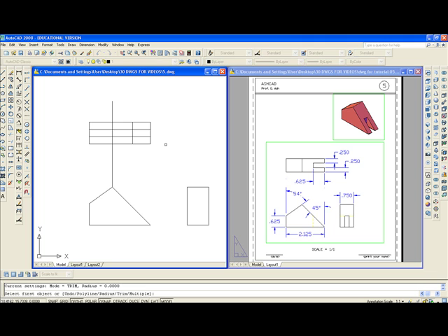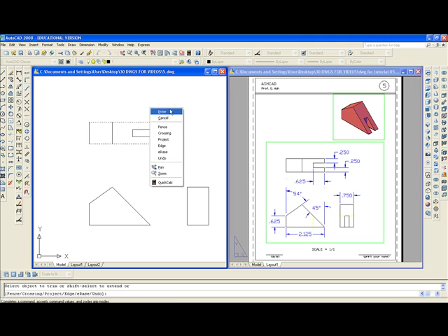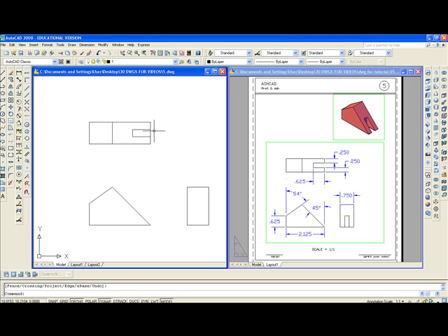Escape, F enter for fillet, and clean up that intersection. We also want to trim, TR enter. Trim from that line and that line, enter. These two lines. This has to be empty. I'll zoom in.